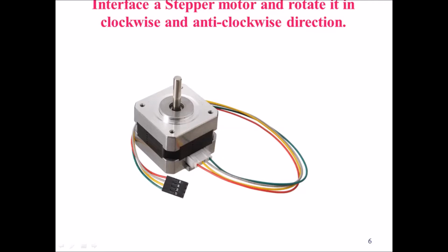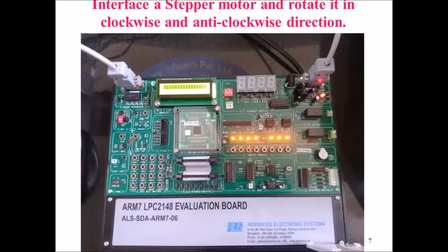anti-clockwise direction. So this is the microcontroller which we are using in our lab. This is the LPC2148 microcontroller. Here you can see this stepper motor interface. There are 5 pins, and 4 pins are connected to the stepper motor. The 4 pins, which I have already discussed, are port 0.12 pin, 13 pin, 14 pin, and 15 pin. All 4 pins come under port 0 of the microcontroller. This is where you should connect the stepper motor.